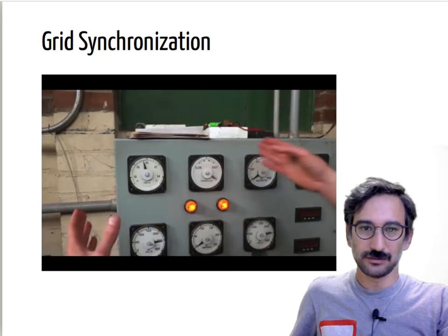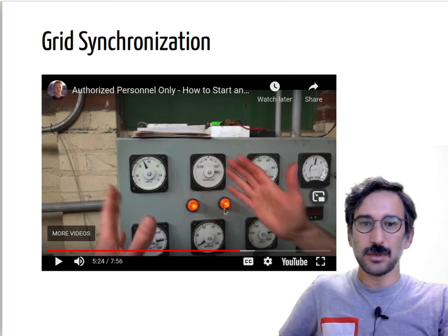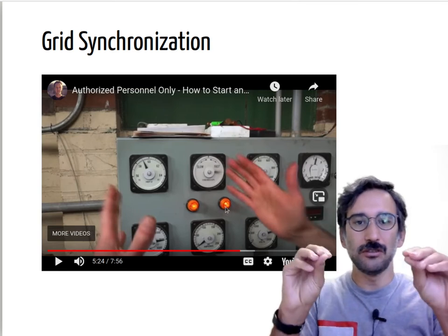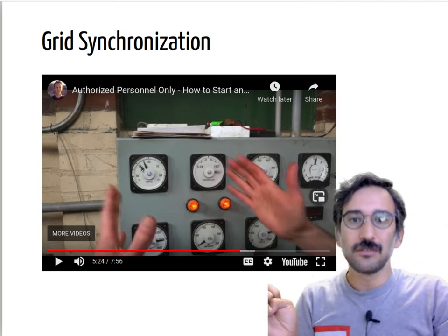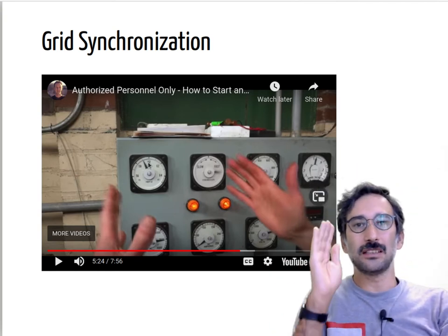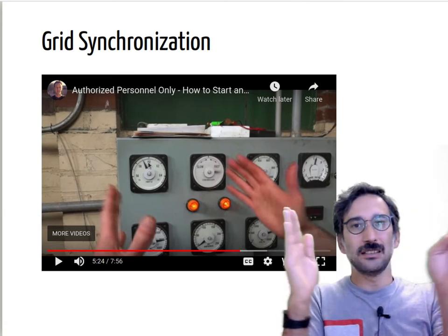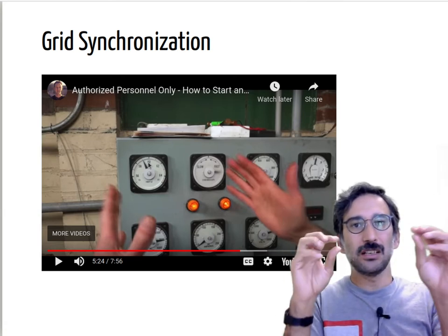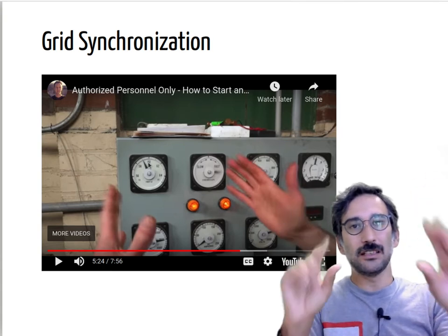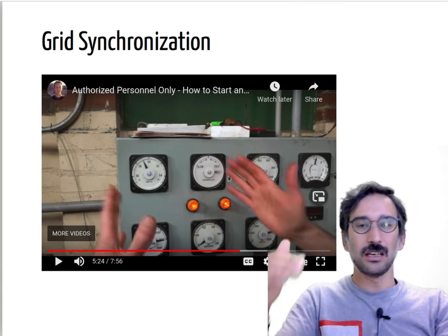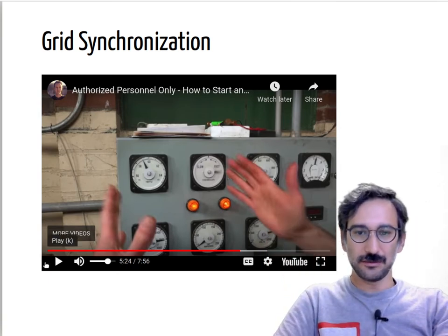Again, the light bulbs are turning on and off, because if you have, say, 59 Hertz on one side and 60 Hertz on the other side, the difference will be around 1 Hertz, so the lights will be going on and off at a lower frequency. If the speed difference increases, they will flash faster.